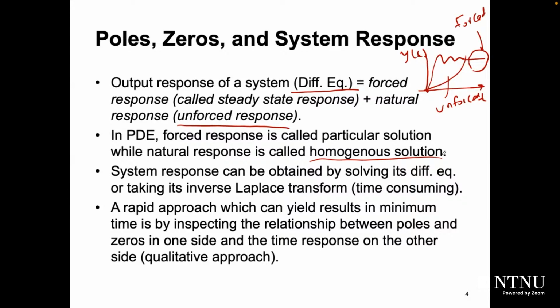So we substitute r of s for a step input or for a ramp, for example, and we use partial fraction expansion to simplify our transfer function as a summation of simpler components. Then we go to the inverse Laplace transform table and try to find expressions in the time domain representing them. So we convert our solution into the time domain, and this will be our solution.